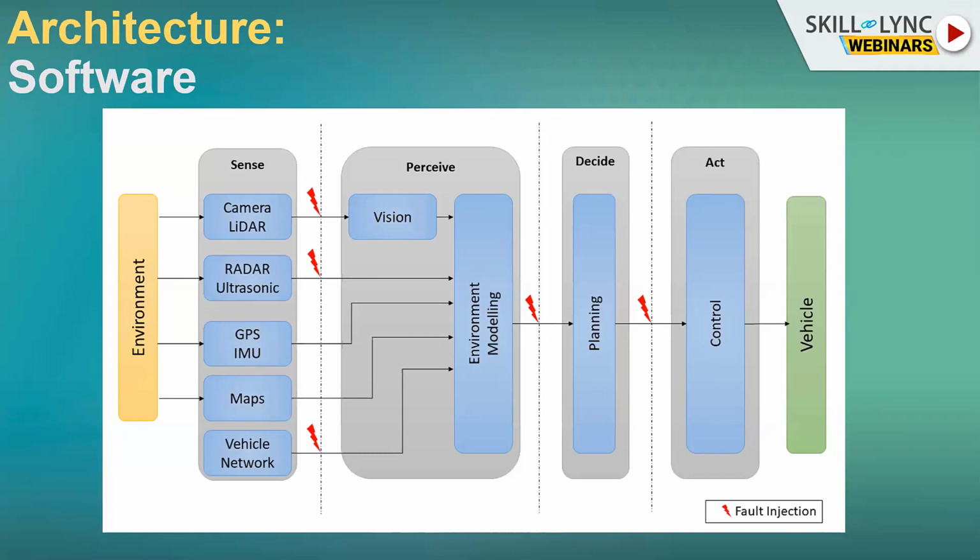The next step is what we call the perception layer, where we are trying to fuse together the data from all these sensors and have an idea about, or basically represent, the environment around myself as a model, where I know that at a given XY location in the world is my car, and I know how far the other objects are and at what speeds they are traveling. All this information is deduced using perception algorithms.